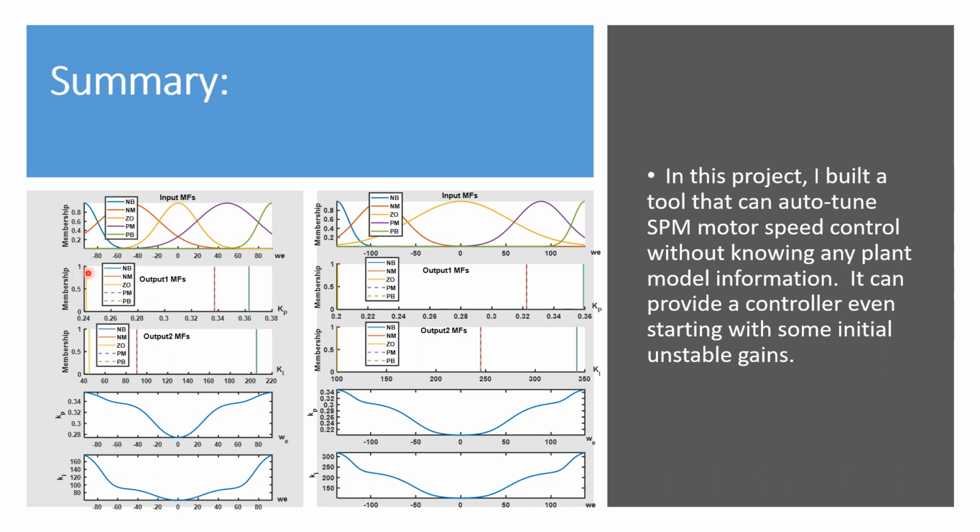And the outputs Kp1, Kp2, Kp3, Kp5 are also free to tune. Of course, the final effect is that every fuzzy logic controller embodies itself into basically two lookup tables, one for Kp and one for Ki.